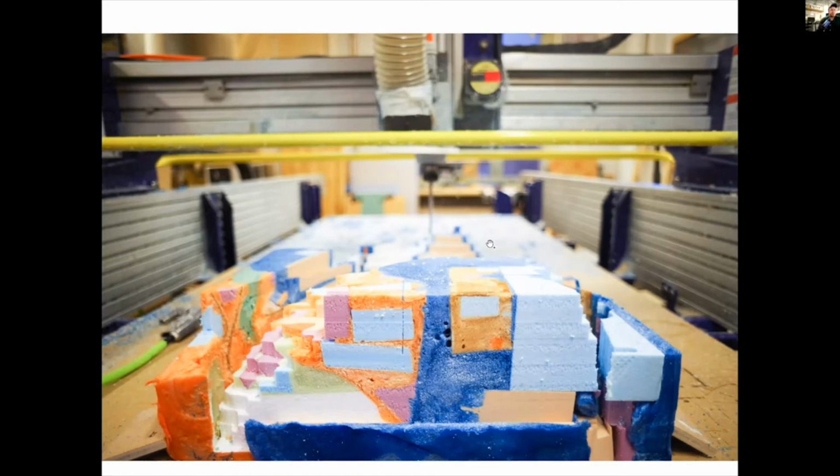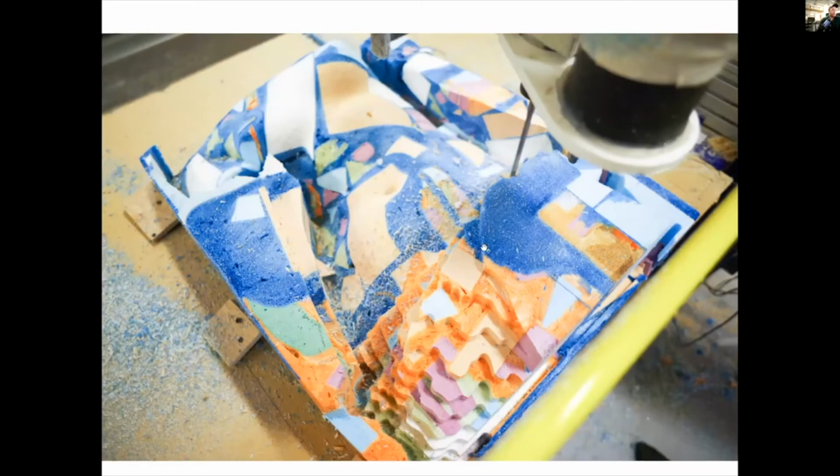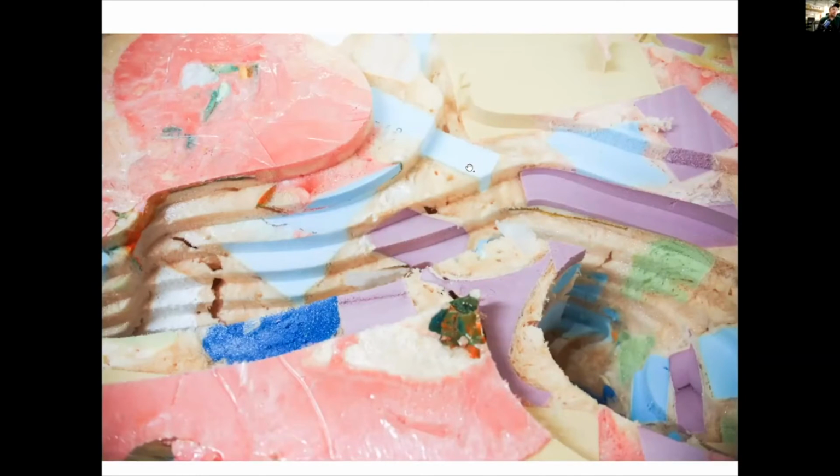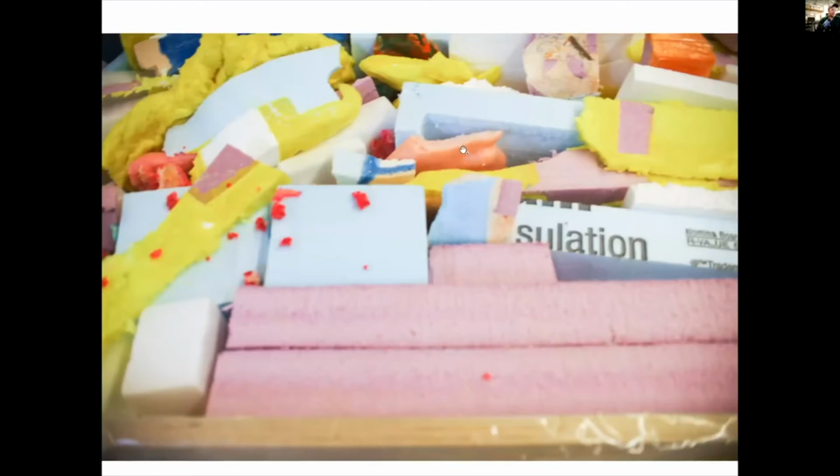What we were determined to do in this project is make a workflow that was as efficient as possible. Through rigging the CNC system to extract and clean up dust in the way we wanted it to, we were able to save the vast majority of the material that came off as waste. That means offcuts, which were the biggest part of the volume, and dust. We saved the offcuts, we saved the dust, and we packed it back into the next mold and made the next block to mill from.